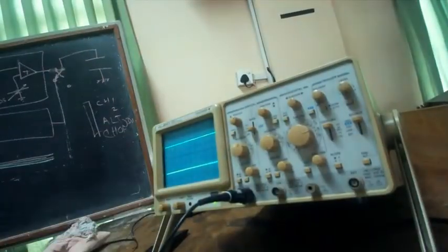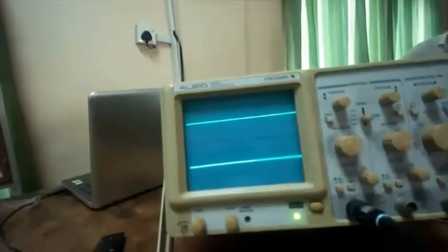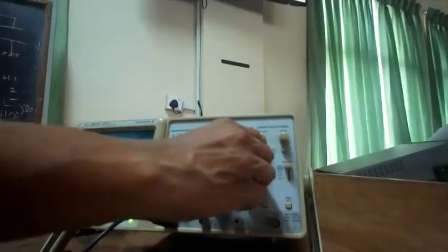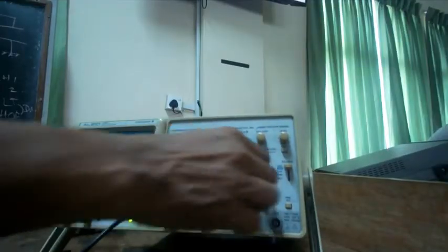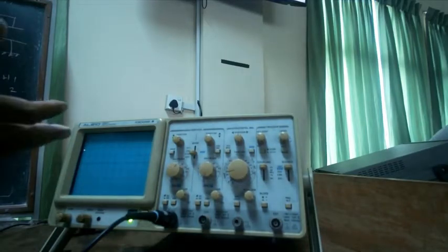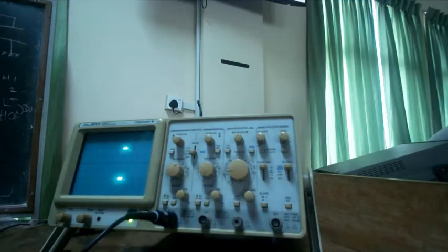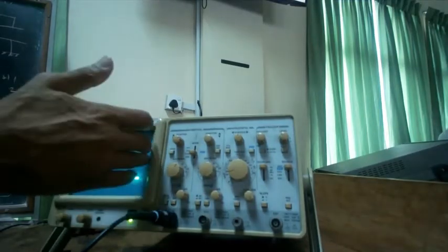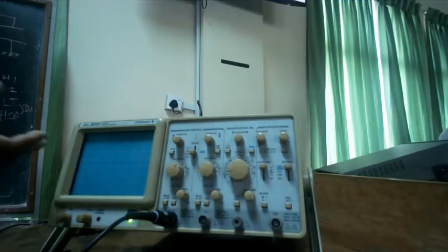That's the chopped mode. In the alt mode, if you switch, you see you don't see that. You draw one after the other. You draw one and then the other. Now, if you make it fast like this, it looks like you are drawing both at the same time, right? This alt mode applies to fast signals. Fast signals means if this duration is very short, you draw one and come back. Otherwise, there's no point doing that.